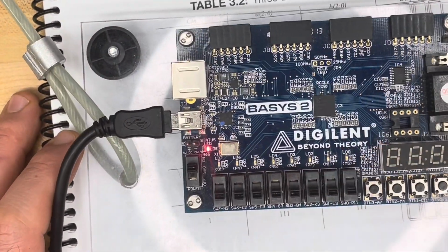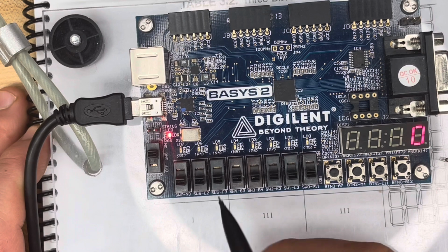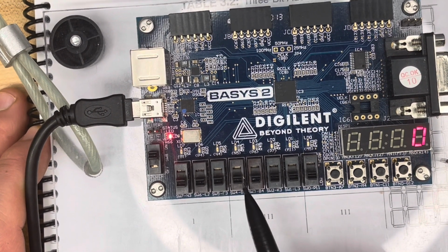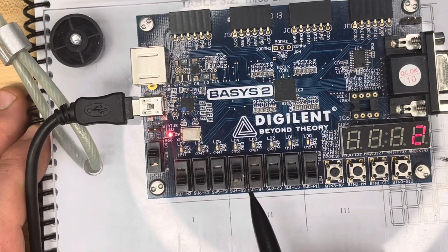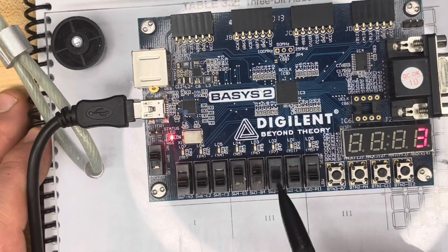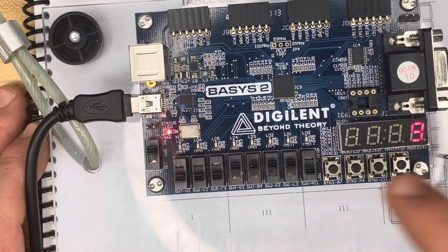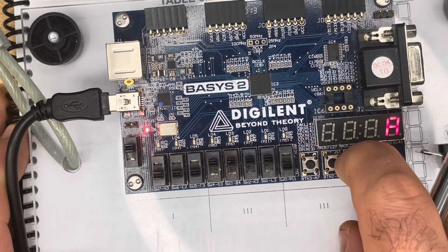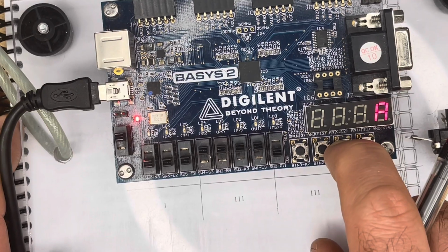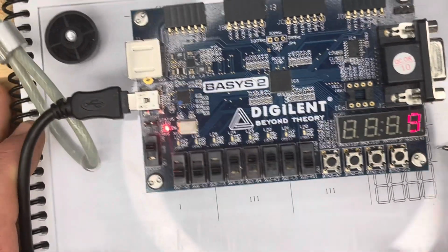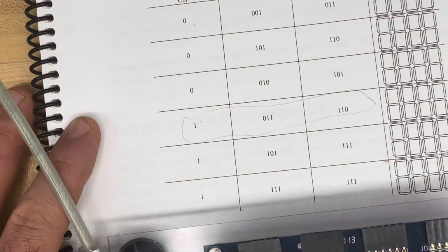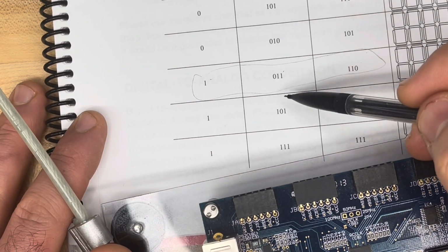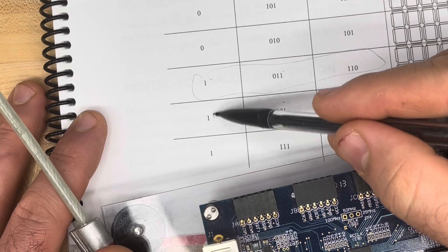Now we're going to do the other case. I set all of them to 0. And then this case is how much? Which is 0, 1, 1, and also here we have 1, 1, 0. So 6 plus 3 is 9, plus 1, the carry in. As you can see, I need to keep pressing the push button. It gave me A. And remember, this is in hexa. Okay? And same thing, we're going to fill the table.